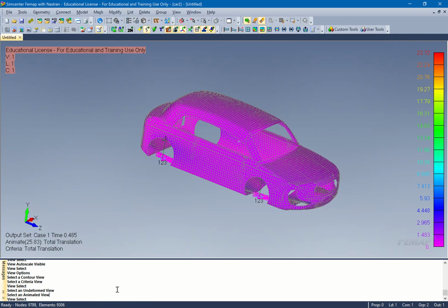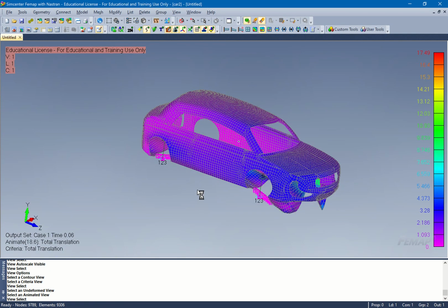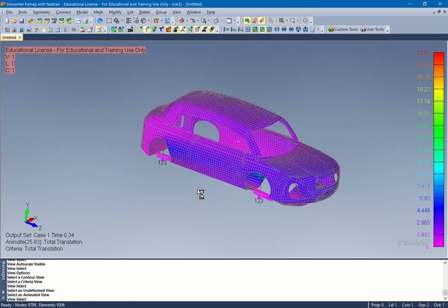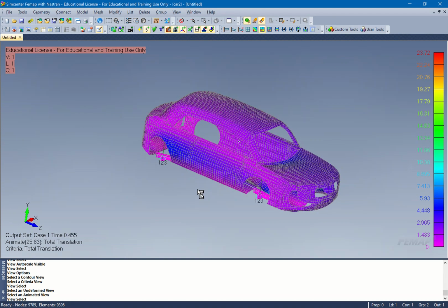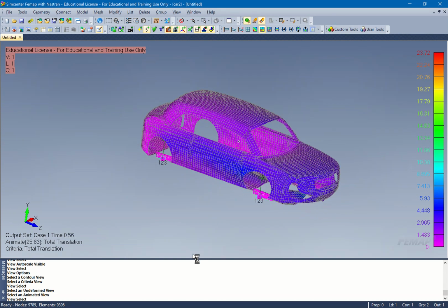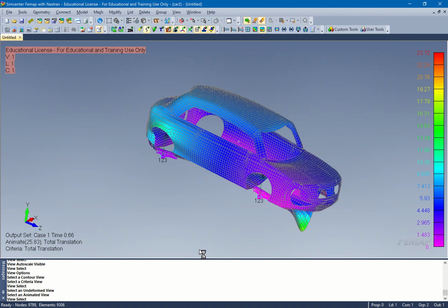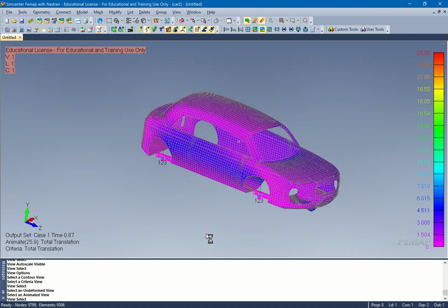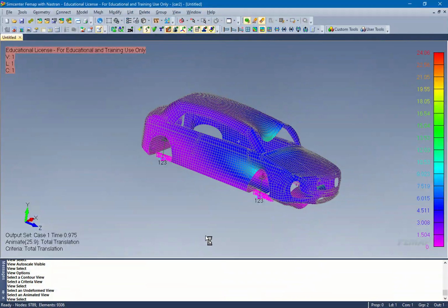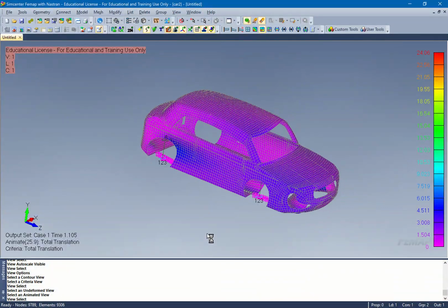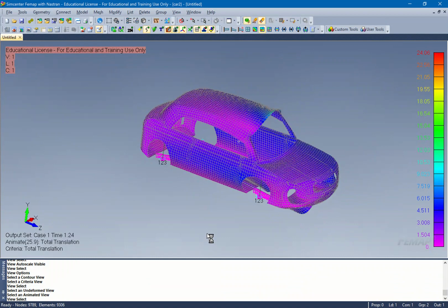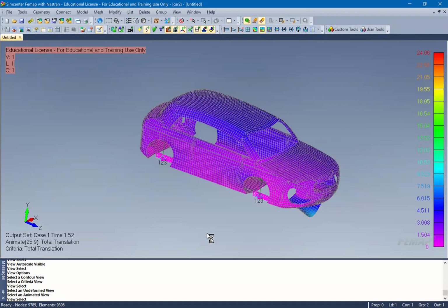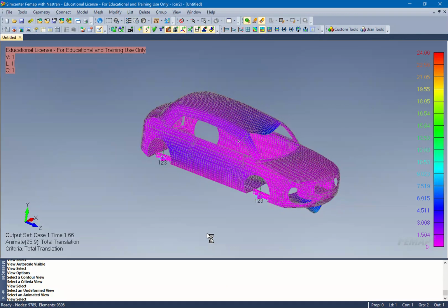Make those between here and here like 10,000. In the V map, it would be the X and Z, so that would be KX, KZ. That makes sense? And then make the vertical one, which would be KY. So KY, we said about 50. Does that make sense? And then constrain this one over here, 1, 2, 3. Then take that load you put up here and put it down there. If I put 50 in the V map, because of all the units we're using, it's already 50 pounds per inch, right? 50 pounds per inch, yeah.